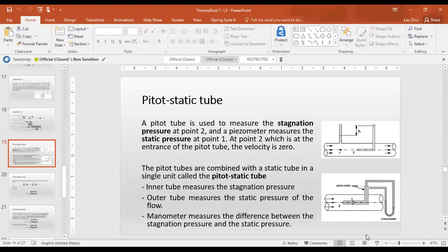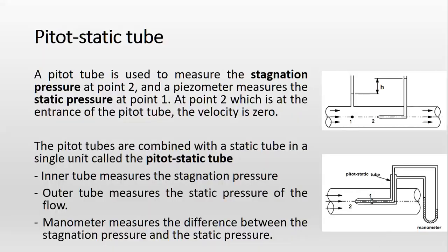Okay, so as I was saying, today we will finish up the last part, which is on the pitot-static tube. The pitot-static tube is also a kind of flow meter. It is usually used in aircraft. This tube will be able to measure the aircraft velocity. Of course, it doesn't directly measure the aircraft velocity. What it does is measure the relative air velocity. So from the relative air velocity, you will be able to determine the aircraft velocity.